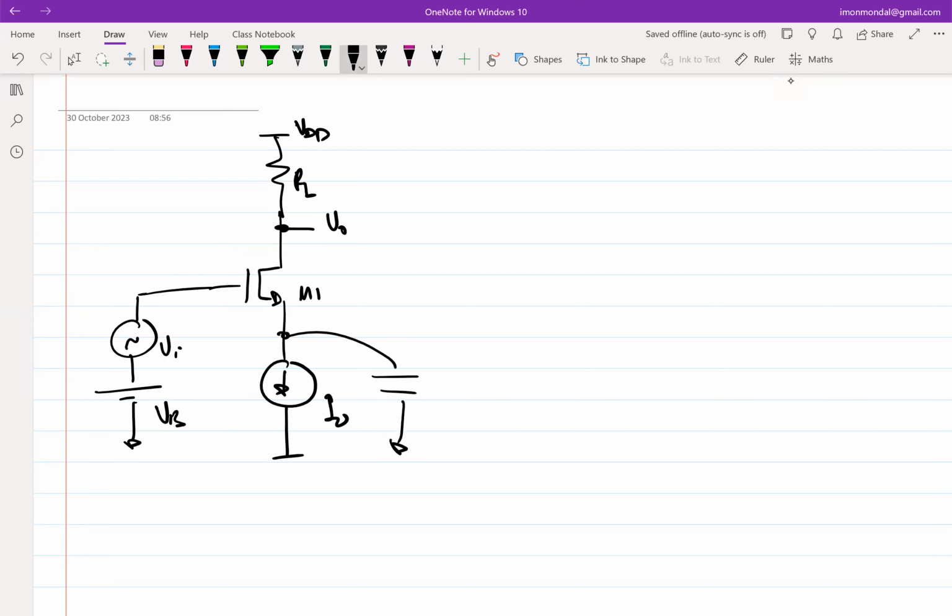So we put a capacitor here, right? Let's call it C infinity. If the capacitor is infinitely large, then for any non-zero frequency, it will behave like a short circuit, right? And then you will have an incremental current. The incremental current will flow through this path, and the bias current, that is the DC current, will flow through this path. So it satisfies both conditions: the transistor is biased using a constant current source, while the incremental current gets a path to flow through the capacitor. Which means the source is moving along with the input voltage as long as the input voltage is DC, but the source is incrementally grounded for any non-DC input.